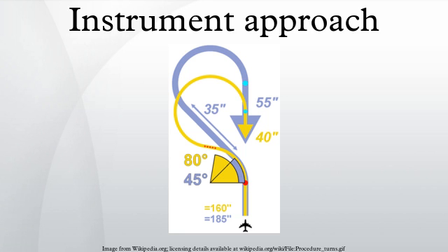Mountain airports such as Reno-Tahoe International Airport offer significantly different instrument approaches for aircraft landing on the same runway, but from opposite directions. Aircraft approaching from the north must make visual contact with the airport at a higher altitude than a flight approaching from the south, because of rapidly rising terrain south of the airport. This higher altitude allows a flight crew to clear the obstacle if a landing is not feasible. In general, each specific instrument approach specifies the minimum weather conditions that must be present in order for the landing to be made.